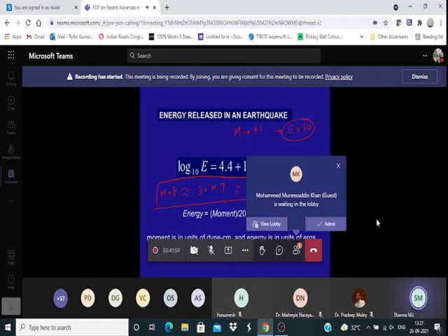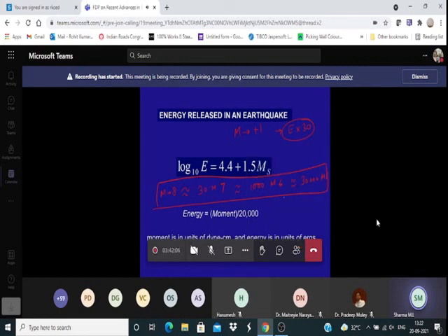And similarly, the engineers sometimes say that, okay, for this building, you take magnitude 7. And then suddenly the next one will come, okay, no, I don't think you should take 7, increase it to 7.5. Oh, this is not just 7 and 7.5. You have increased the load by 15 times. One should understand that there is a hell of a difference between magnitude 7 and 7.5.